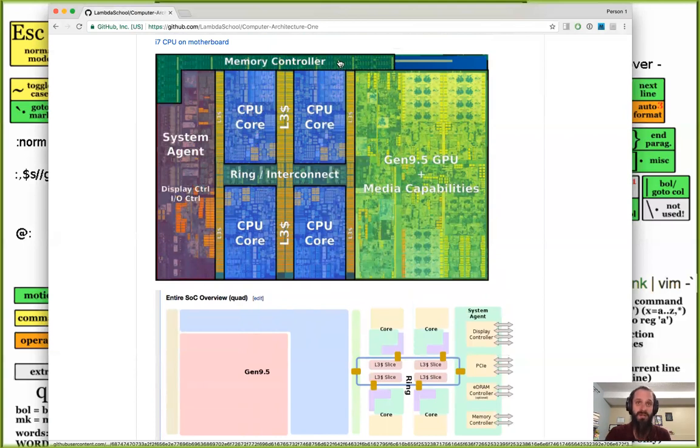and they have to share this memory controller, and they have to share this GPU, which is kind of like the built-in Intel 4000 graphics processor. It's way better than not having a GPU, but NVIDIA's version of this GPU is 30 times bigger. It's the same thing. It's got 30 times as many of those elements inside of it, and they're connected over DMA. All right, this ring interconnect in the middle is transistor circuitry that enables the CPUs to talk to one another. That's what that circuitry is for. And the CPUs have their own private messaging system. They have their own private language that no one on Earth knows, except for the people who work at Intel who built it.